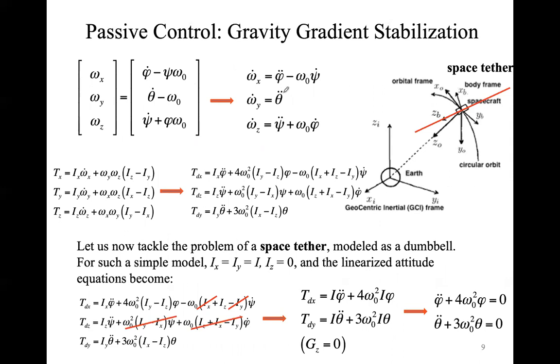Our goal is to arrive from the dynamical equation expressed in the general form with the Euler equations, by using the small angle approximation in roll, pitch, and yaw axis, at this final configuration here. Tomorrow we are going to deal with this linearization because it is fundamental to determine the stability of the system.